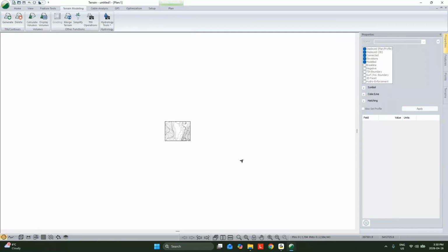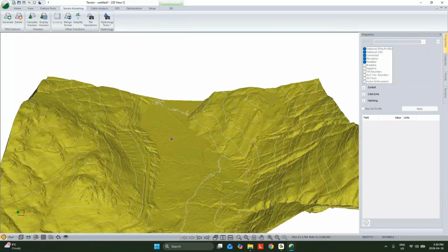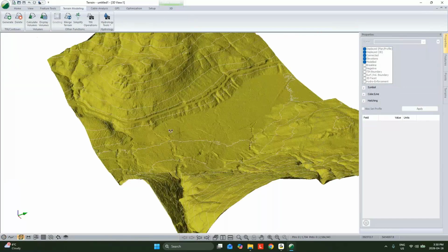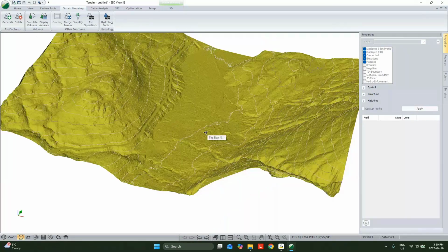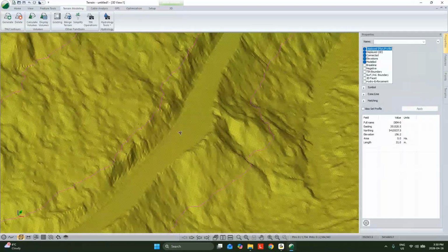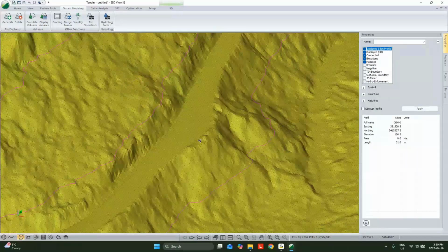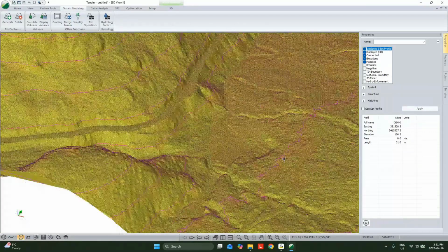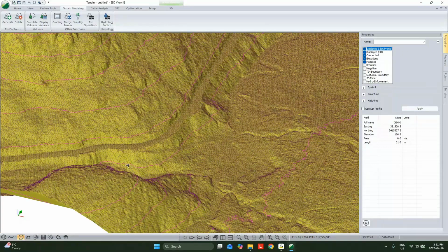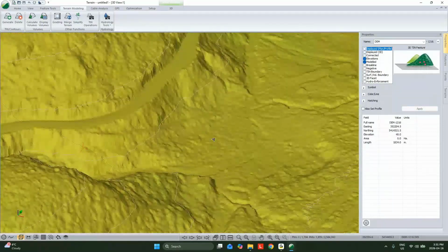And I created my contours this time too. But we can check out that 3D surface, and it's pretty similar to the last data. Now, the difference being that we have our points on a regular grid, so a 1 meter regular grid in this case, so it's dense enough that it does a good job of capturing our details. Now, it's not adding any details if there's gaps in that original LiDAR data. We still get a point right on top of wherever those longer triangles would be.